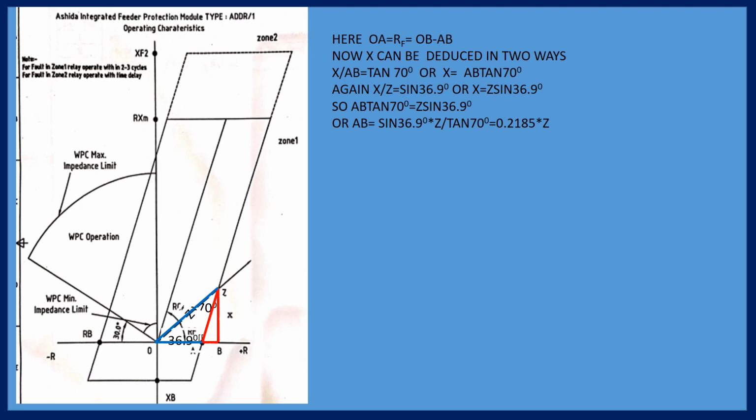You have thought that the isolator is closed, but during maintenance you have opened the isolator, so the other side will not get the earthing. A discharge rod is not provided at that end, and the man working there will get shock. So the sectioning point is a dangerous thing. Keep alert that each section is to be protected with two dischargers.